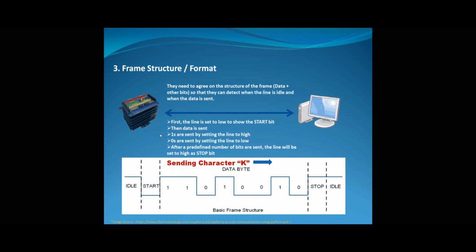When we were on the TX side and we were basically just sending out data, if you remember, I explained that we need to set a start bit, basically bring the line from idle to low, and then after that we could send the data bit by bit on the line. Now here, because we are on the receiving side, we need to somehow detect that start bit on our side. So when the PC is sending the data, we should be able to detect the start bit, and then right after the start bit, we should be able to pick up the data.